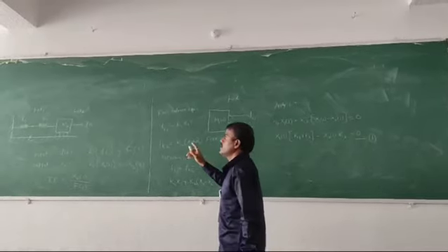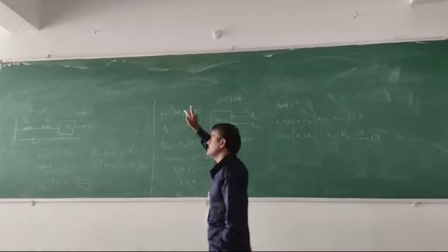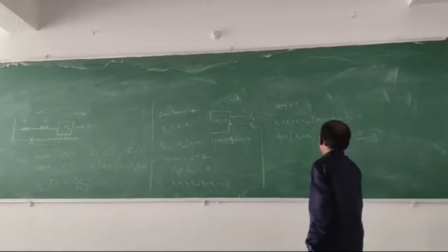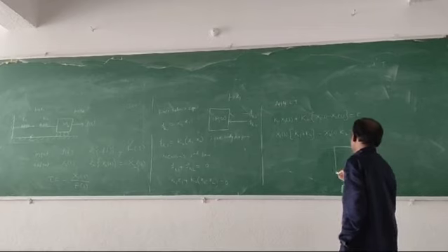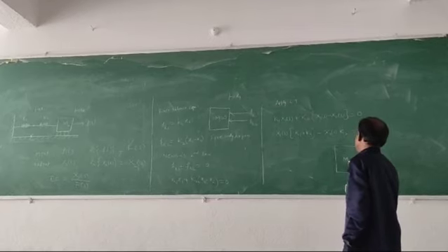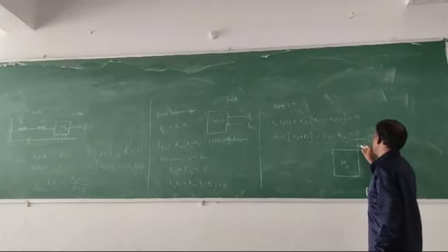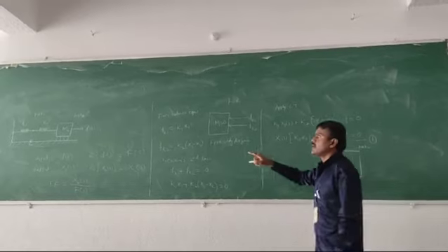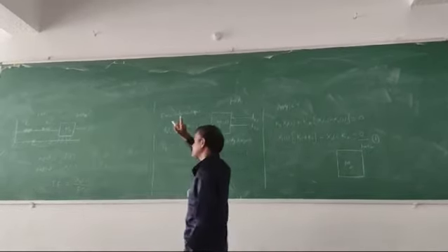In a similar way, now we are going to write the force balance equation for the second mass element. So first, draw the free body diagram of the mass element. The displacement of M2 is x2, and here on M2 we are applying the direct input force.